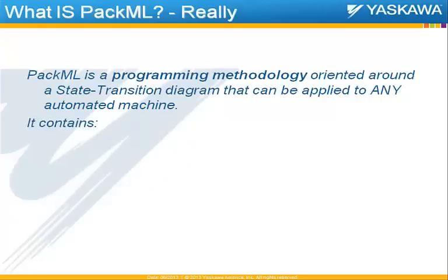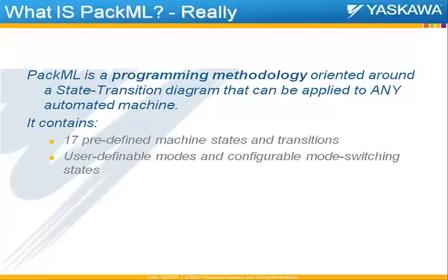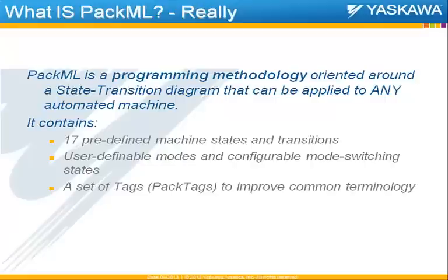So what is PackML really? And I don't mean really like the Saturday Night Live, you know, really? Really? I don't mean it that way. What I mean is, in reality, PackML is a programming methodology oriented around a state transition diagram. And it's my opinion it can be applied to really any automated machine or process. It contains 17 predefined machine states that we'll go into detail about, user-definable modes and configurable mode switching states, and a set of tags that goes with it. And a good ancillary feature of the PackML spec is a spec for naming conventions called pack tags.